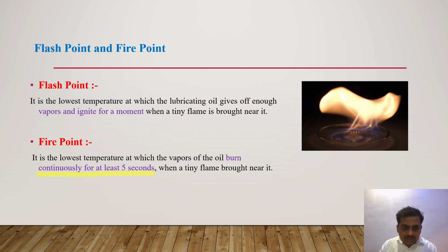When we get the flash point, after that we get this fire point, and it is generally 5 to 40 degrees Celsius above the flash point. So the flash point is reached first, and after that the fire point is reached.